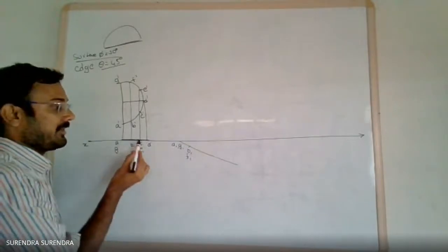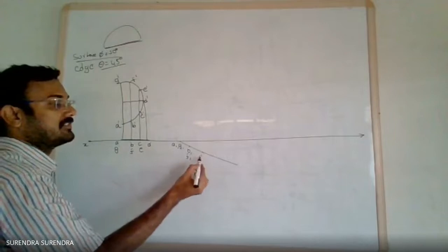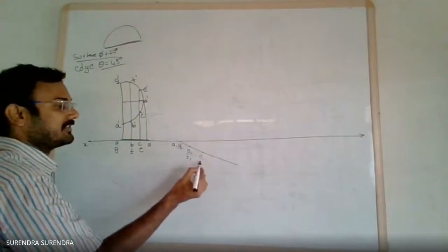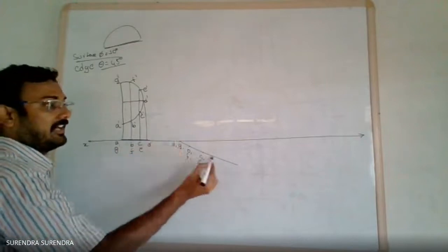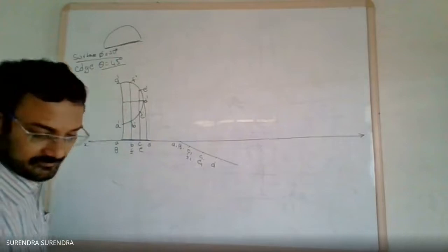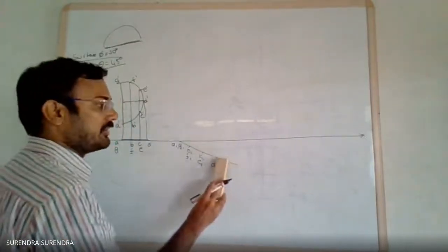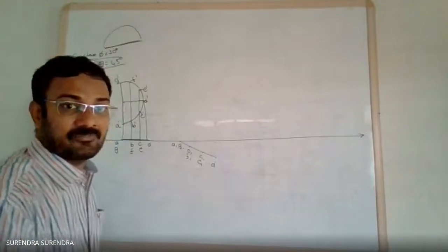Measure the distance from A to C, with A as center draw the arc. This gives C1, E1. Measure the distance from A to D, with A as center draw the arc. You get D1. Leave the remaining line with 2H, and erase the excess.